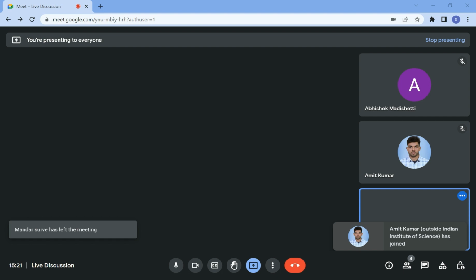So here when they are saying that they are given true length and this true angle 45, I can only see it in a special case when the line is either parallel to HP or parallel to VP, depending on with respect to what the angle is given. So here they have given that it has 45 inclination with respect to VP. So it is a line like this. I can see this 45 degrees only when I have this line parallel to the horizontal plane.